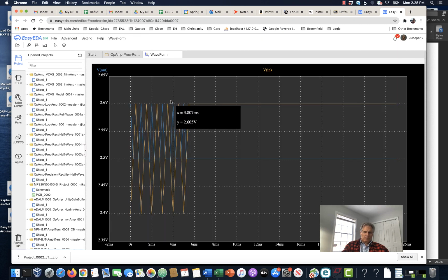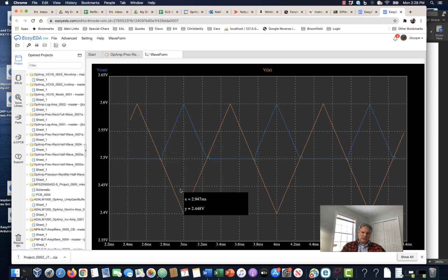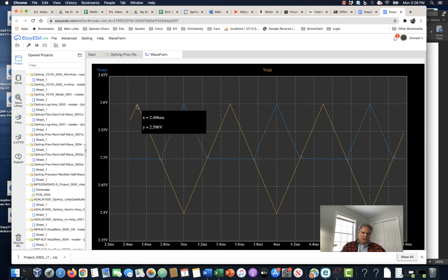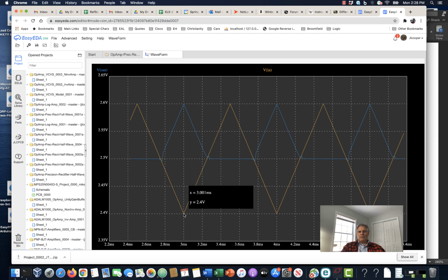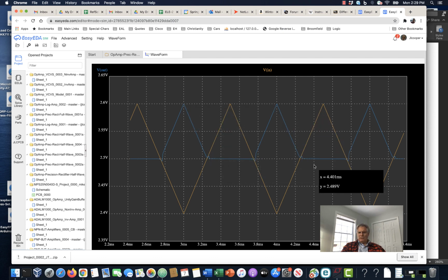Alright, so I'll just grab a couple cycles worth of this thing. So yeah, we get an inverting half-wave rectifier. Here's our waveform, which is a triangle waveform. It goes 0.1 volts above 2.5 volts and 0.1 volts below 2.5 volts. So it's got a 0.2 volt peak-to-peak swing. But in the section that goes below, and again, there's some funny business here on these corners, on the blue output waveform, we half-wave rectify this, and we just drive out the half of the waveform.